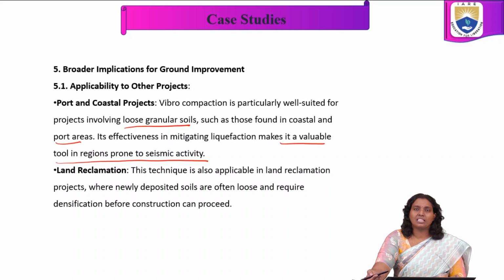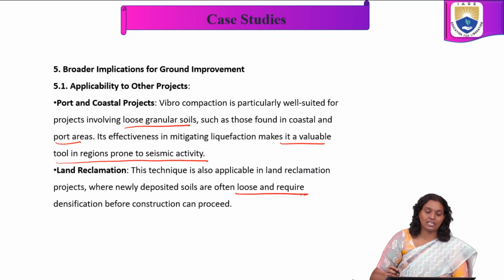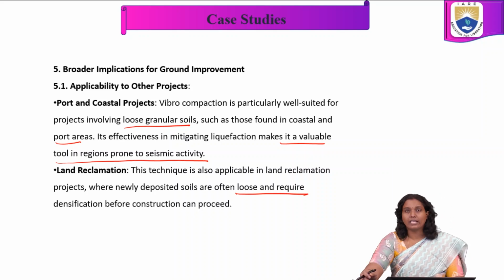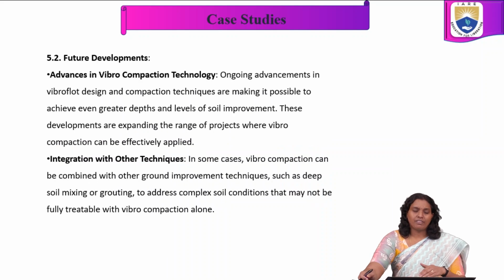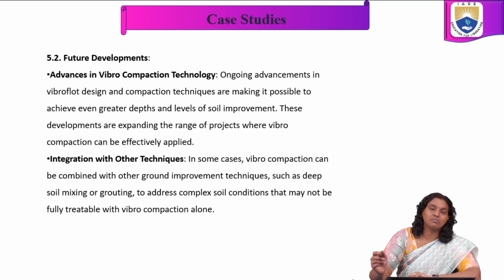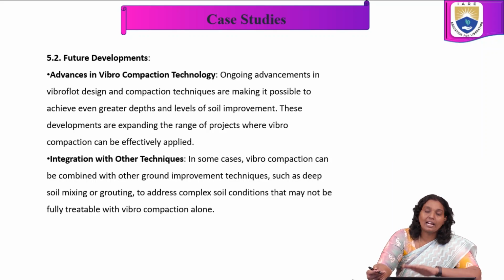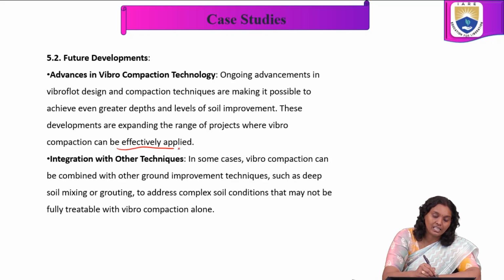Land reclamation: this technique is also applicable in land reclamation projects where newly deposited soils are often loose and require densification before construction can proceed. As for further developments, ongoing advancements in vibroflot design and compaction technique are making it possible to achieve even greater depths and levels of soil improvement. These developments have expanded the range of projects where vibro compaction can be effectively applied.